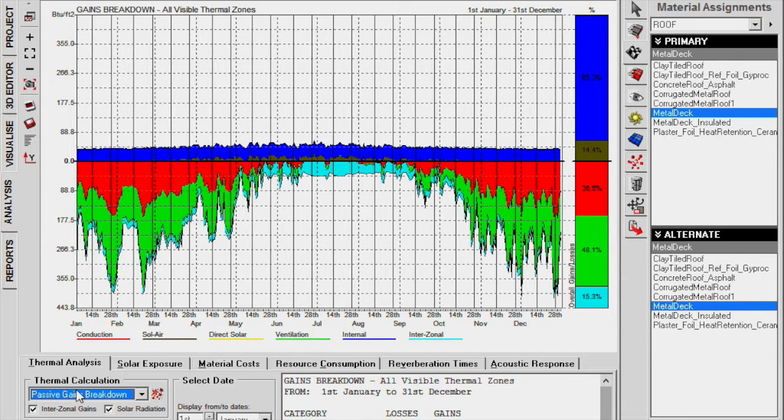They actually have windows now, they're right around 0.3. So on this scale of 0.05 and 0.07, kind of around 0.30, something like that. Not too bad. Not as good as a fully insulated wall, but not too bad. They can actually get windows that are much, much even better. You know, they're getting them down to 0.20 and 0.15 and things like that. So you can really get some very nice high performance windows that are almost as good as walls. And those will address the issue of conduction.